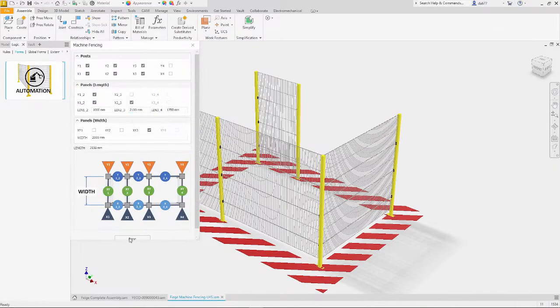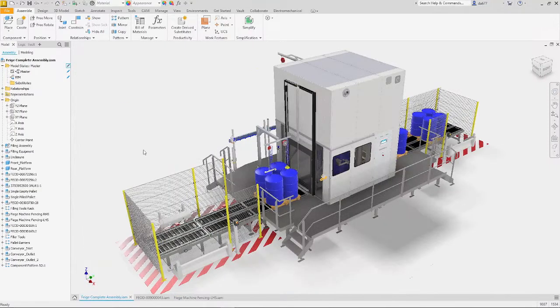They're going to add an extra 200 millimeters and the design updates. All through iLogic for the model changes within the design. Vault copy design to duplicate the original conveyor, to shorten it and place it outside of the platform.